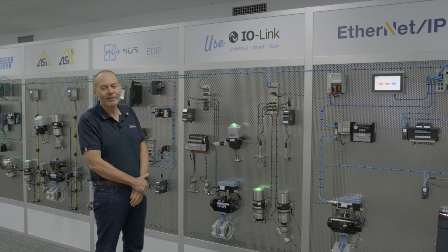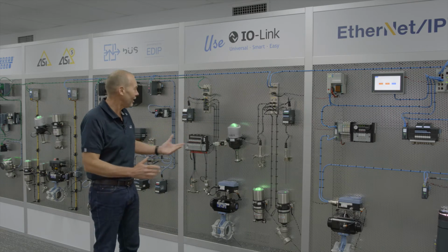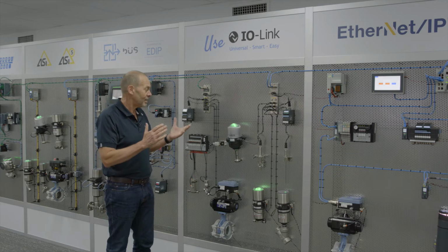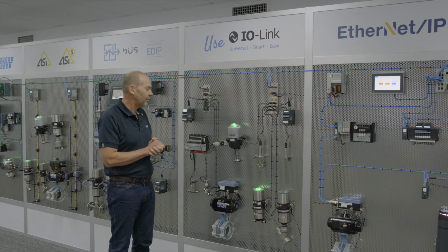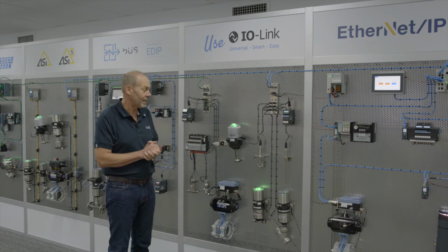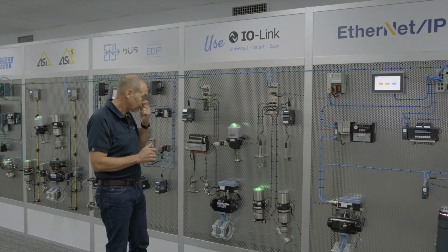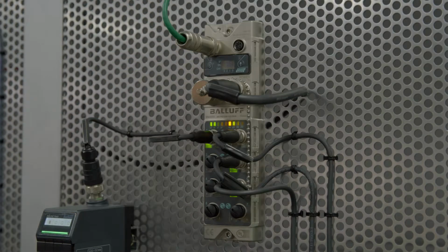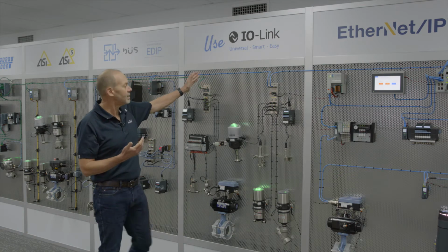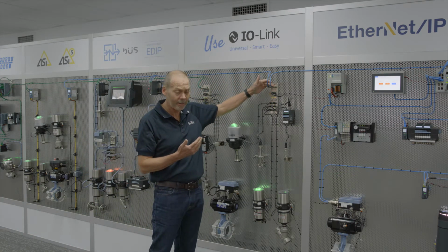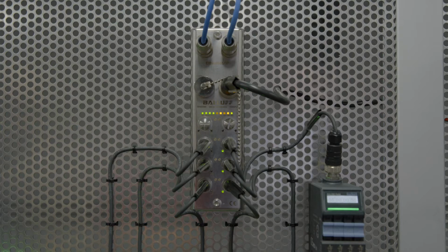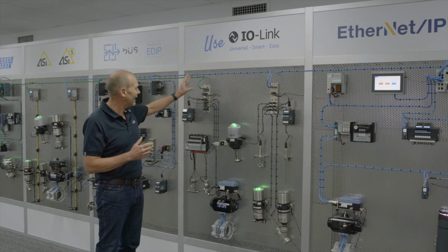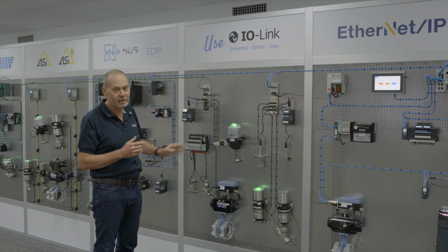Welcome to our digital connectivity video on IO-Link and connecting IO-Link in the field. IO-Link has been widely accepted in recent times simply because it's a very capable and yet very simple network to understand and to deploy in the field. It generally consists of blocks that are talking onto a main network like Profinet. In this instance, we have Ethernet IP. It could also be Profibus, CC-Link, or other networks. So it's a sub-network where we link these field networks to individual devices.